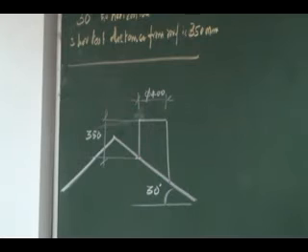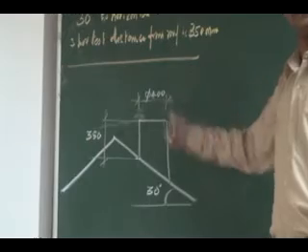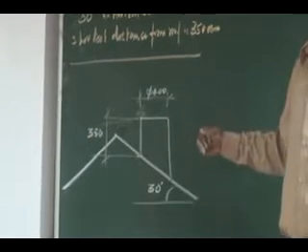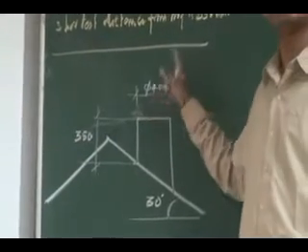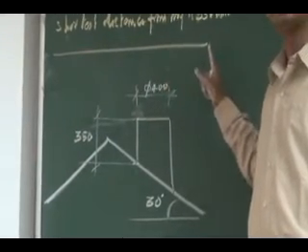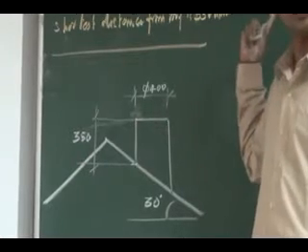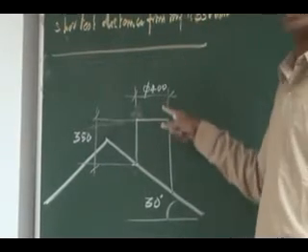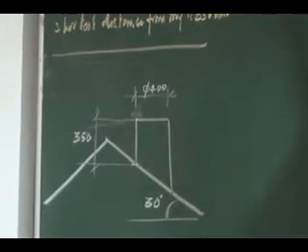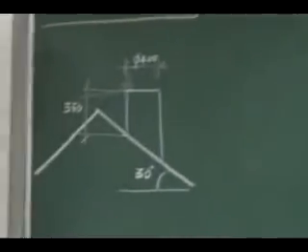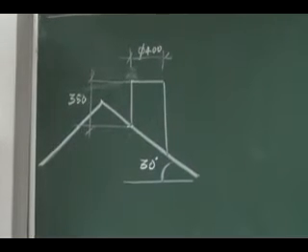Can you draw it in your drawing sheet? No. So what you have to do is adopt a scale. What scale can I go for? I can reduce the size, so a reduction scale I can adopt. 1:10. So what you are going to draw as 40, the actual is 400. Carefully you adopt a scale. In the problem it will be given: use appropriate scale.